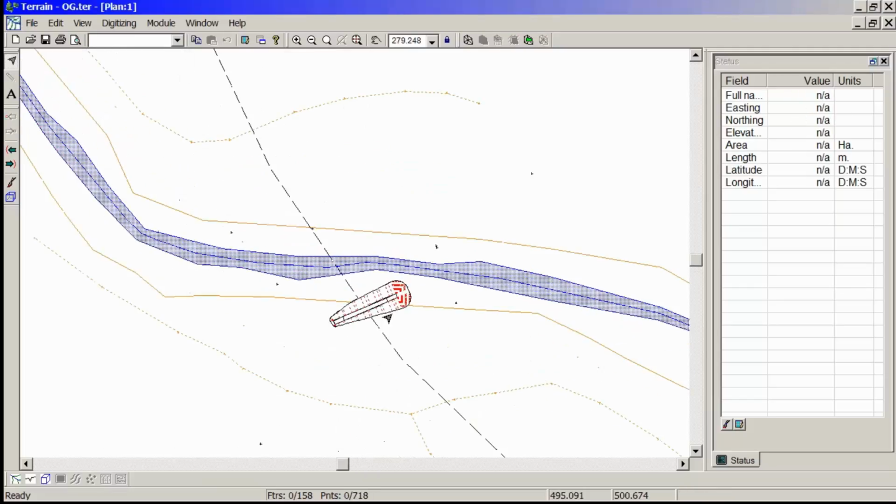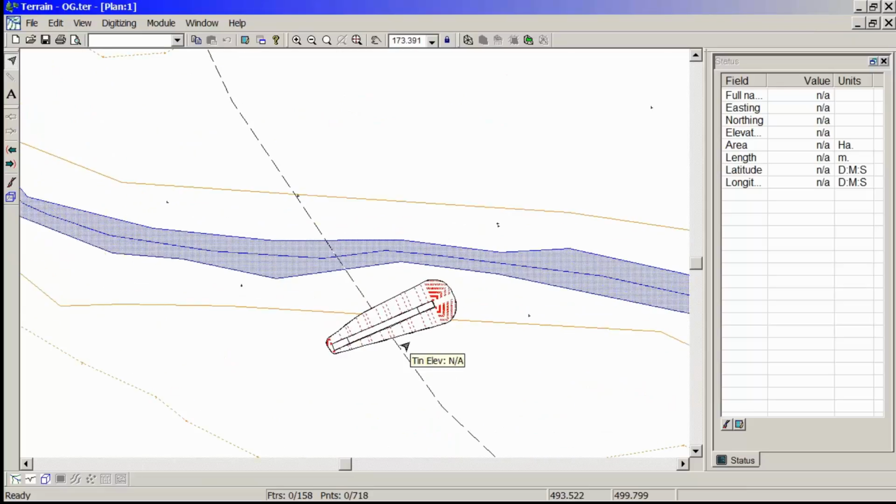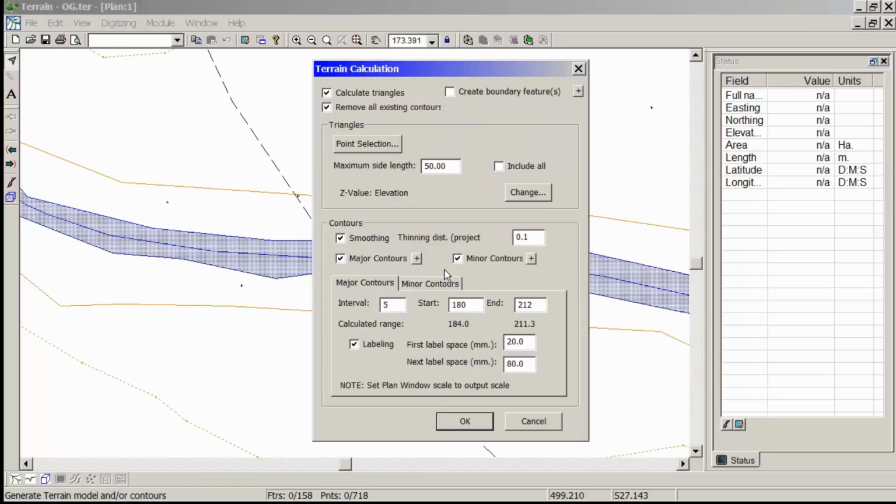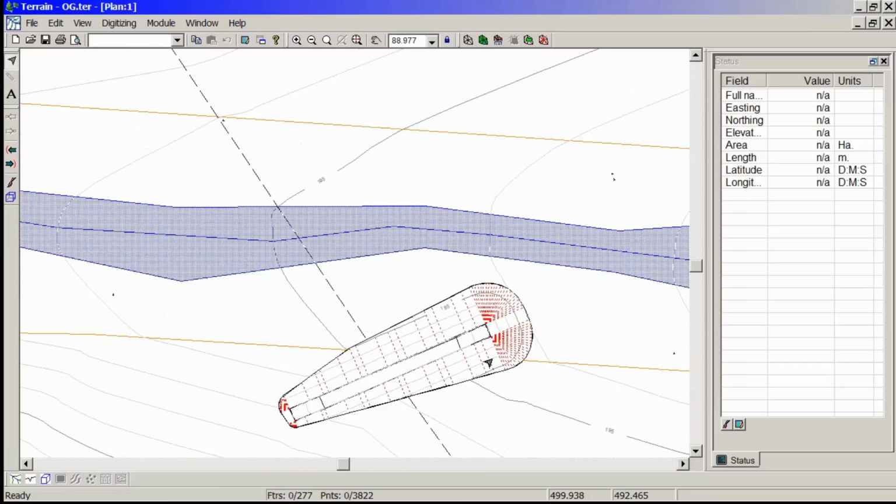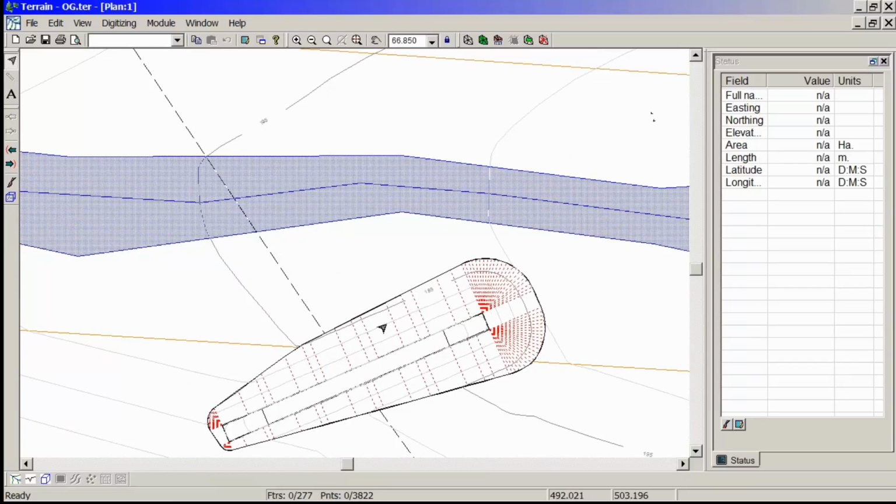So what this did was basically, like if you've seen other examples of ours where we've graded and merged, for instance our pad design, it created a hole in this area, got rid of all the old data, and merged in the new south abutment. Next step is to generate my tin contours. You can see that the contours follow circular around the base of that fill.